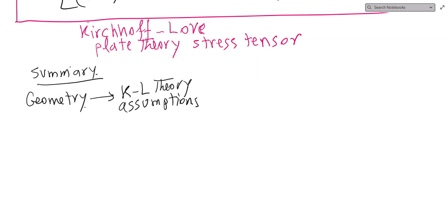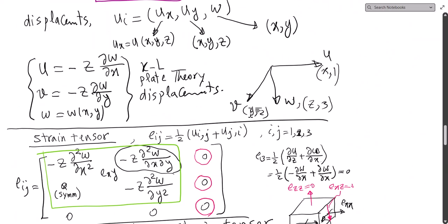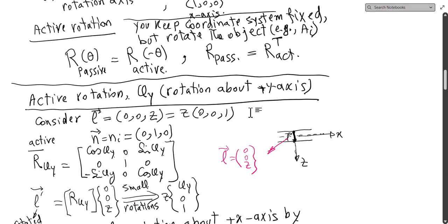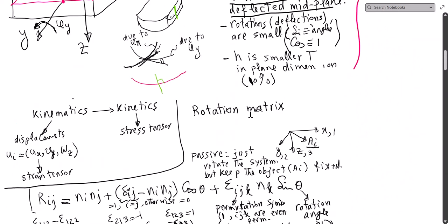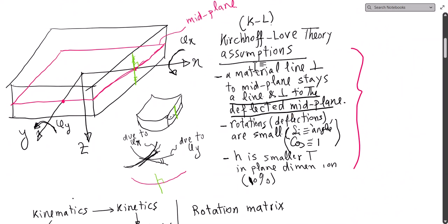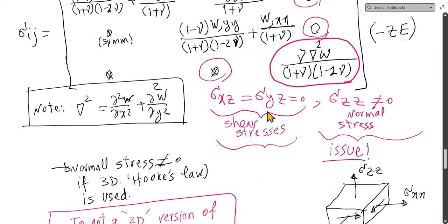And the key here is that once you impose these assumptions on your kinematics, the kinetics should also comply or be justifiable. Sometimes this problem is not easy, and if you get very constrained assumptions in the geometry, then your kinetics will suffer. And if you relax this, the whole thing becomes complicated. And that is the dilemma that we have in both beam theories and plate theories.